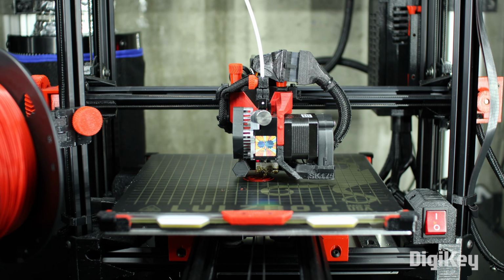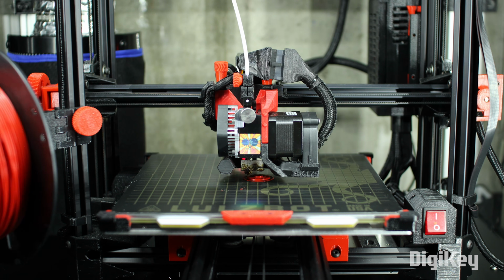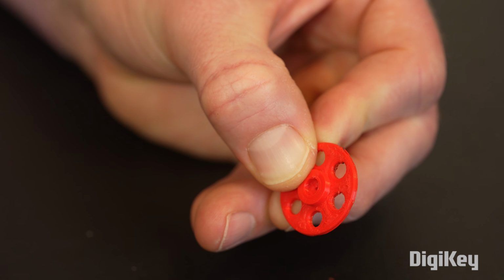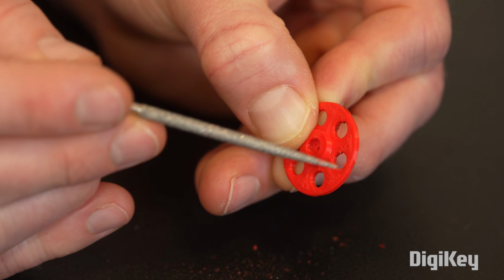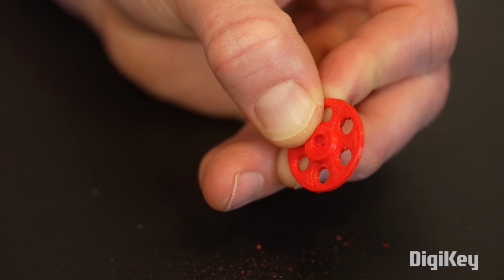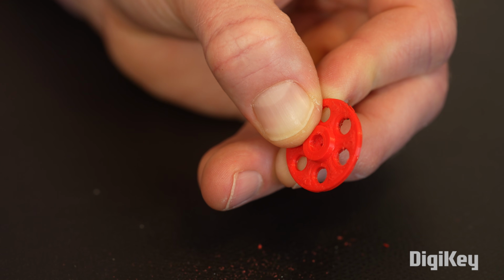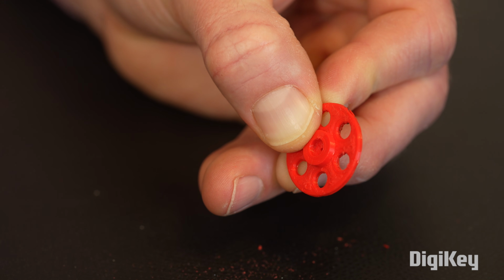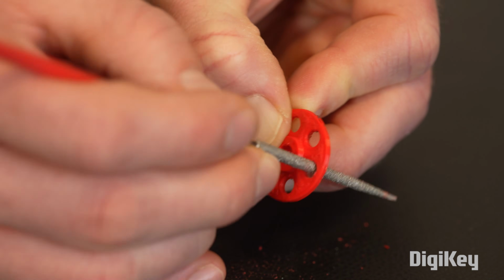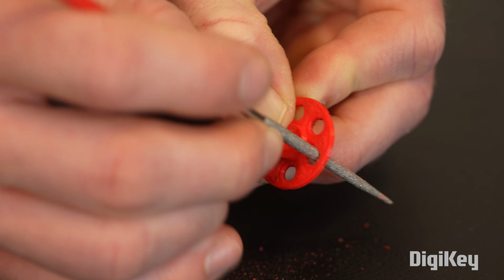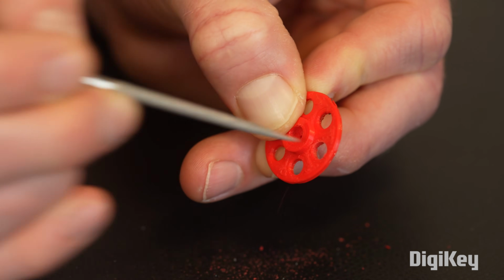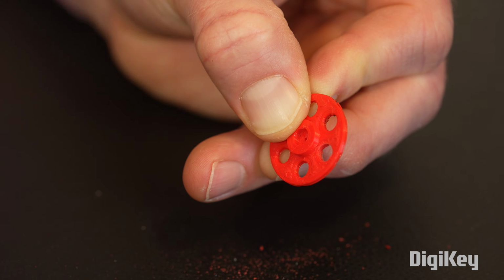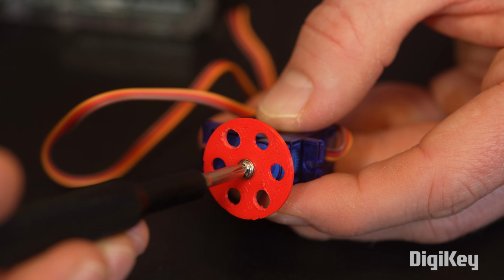As this is a small part, the print should be pretty quick. Most FDM 3D printers have a little bit of squish when the plastic is extruded. Also, the axes aren't always very precise, at least not to the precision that LEGO components are made. You might need to use a small file or drill bit to clean out the holes for a good fit. If that doesn't work, you might need to adjust some of the dimensions in your model and reprint. With some luck, we can get everything to fit together.